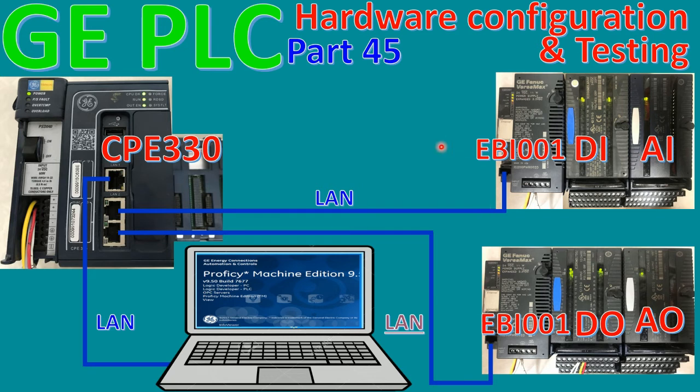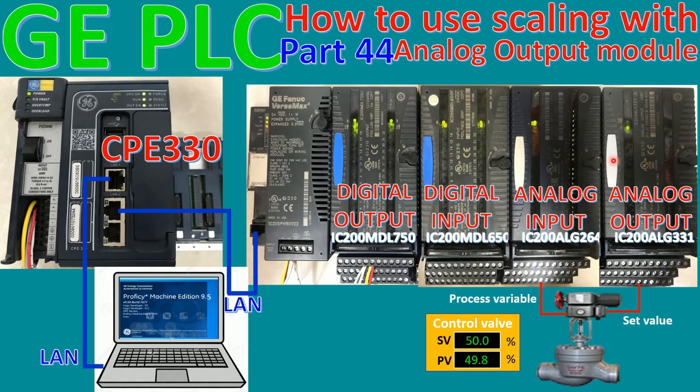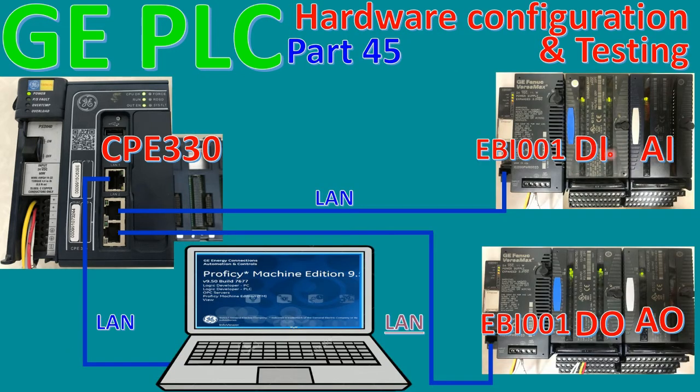And for remote I/O number 1, I will keep the same as the IP address that we already learned in the previous video. So I just cut the two modules from the previous video, yes. And then I will adjust to be the same here.